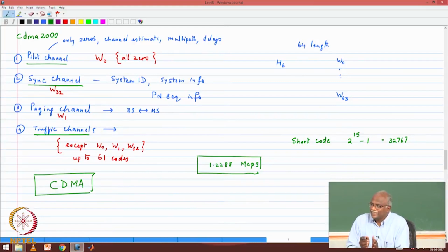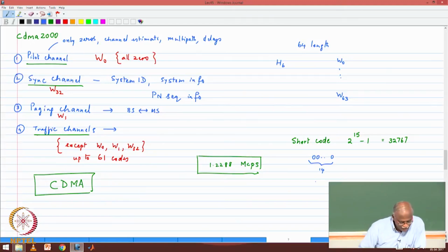What that means is they have to insert one bit, and that bit comes after the one occurrence of a run length of 14 zeros. Somewhere in the sequence there will be a run of 14 zeros; 15 zeros can never occur.